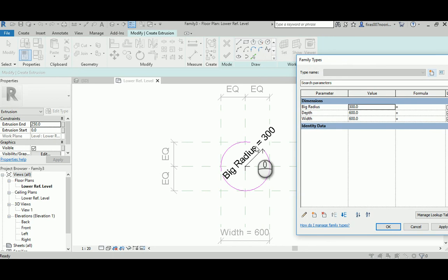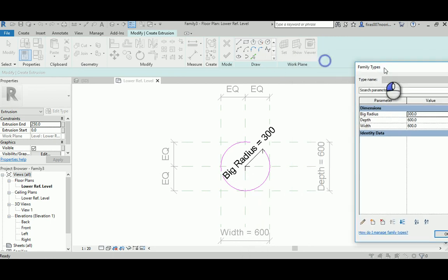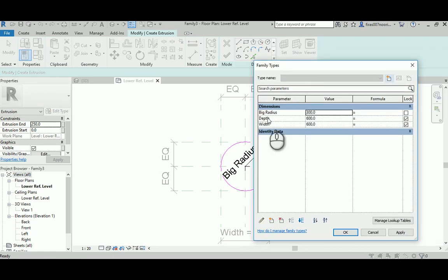it could be a rectangle, not only a square, and I don't like that. In the design that I want, it's a radius, so the width should be really equal to the depth. So come to the depth and just give it the width value. So whatever you change, let's say this is 300, you see, it's gonna change the depth, and when you change the depth to 400, it's gonna turn the value back to the width, and so on. So that's what we want. We basically want to make a square, not a rectangle.